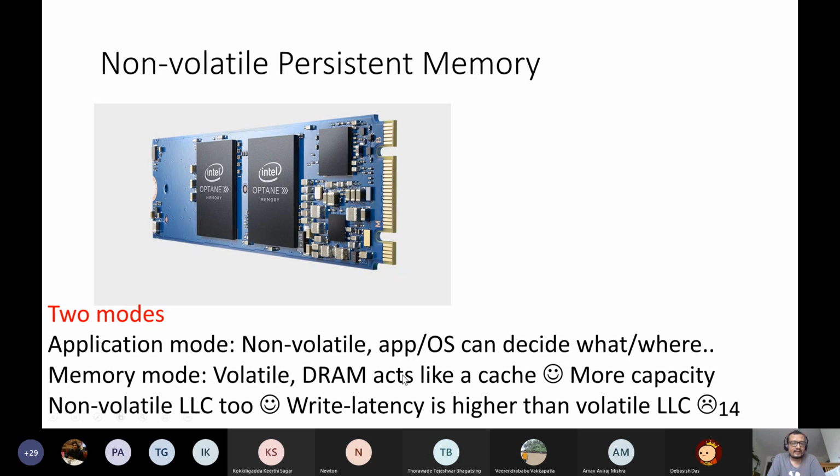Similarly, the latency also goes for a toss, and that's how it affects the bandwidth. For a given load, let's say a typical DRAM takes 100 cycles, now it will take 400 cycles. So that manifests in terms of bandwidth. You pump less and less data in more and more time.